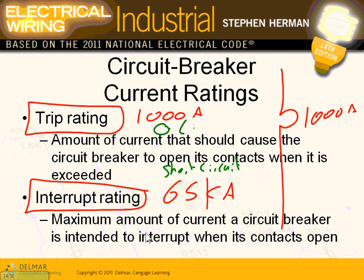What that means, guys, if here's 1000 amp and I have 2000 amp pulling out of this system, which one do you think is going to trip? The trip rating is going to trip. If I have a short circuit or a ground fault and I pull 15,000 amp out of this, which one is going to take care of it? The interrupting rating. One component for the overload, one component for the short circuit, always. We're going to look at the curve in a second here, but please be aware of that one.